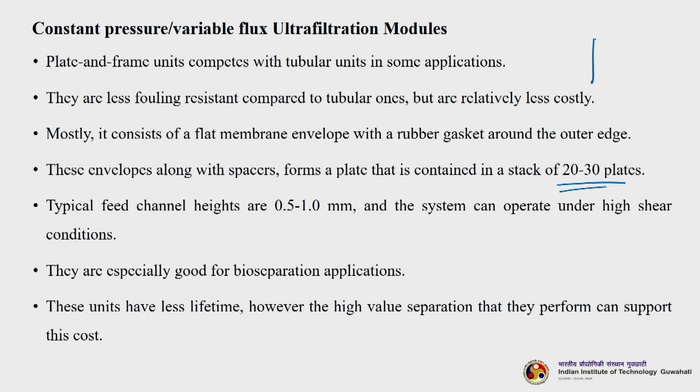One single plate I am trying to show something like this. So, it is a single plate. You can have many such plates, thereby making a stack of plates. Usually a stack contains 20 to 30 plates. Typical feed channel heights are 0.5 to 1 mm and the system can operate under high shear conditions.